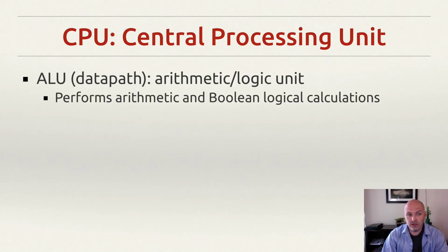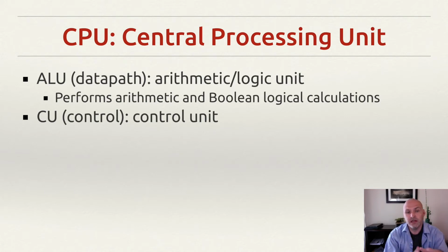So we mentioned that ALU, right? That's part of the data path, and we know that it provides the arithmetic and the logic unit. So arithmetic is usually part of an adder. An adder allows us to literally add two numbers, but as we'll learn later, if we use signed numbers, we can also use an adder to subtract. So for example, if I add the numbers 4 and -2, I am effectively subtracting 2 from 4, even though I said that as let me add a 4 and a -2, right?